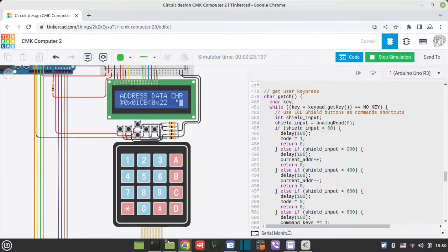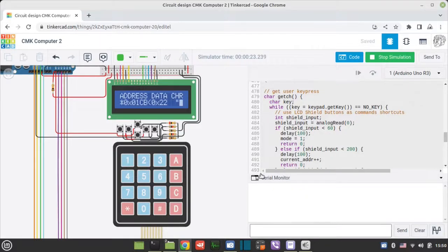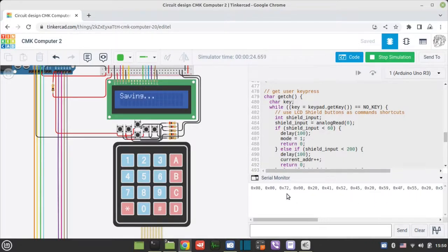So here, for instance, if we have a look at the serial monitor, and I say B, then I'm saving bytes to the serial monitor, and it takes quite a bit of time, but eventually whatever program you've written in the emulator would be sent in here. The problem is that you can't really do the opposite: you can't load via the serial port into the emulated one, because it only supports sending ASCII characters and not raw bytes. So that's an issue, but there is a workaround.